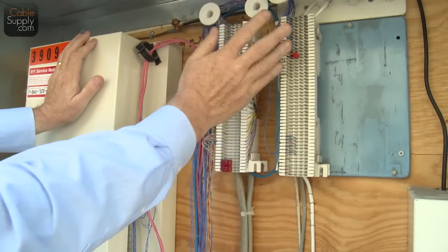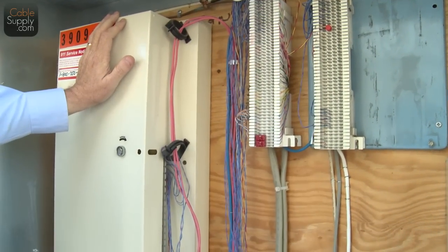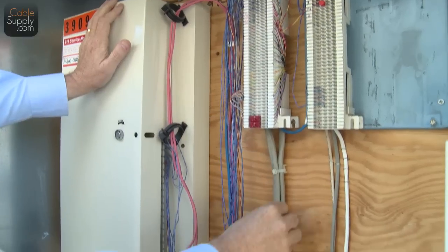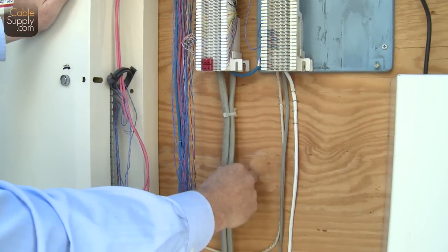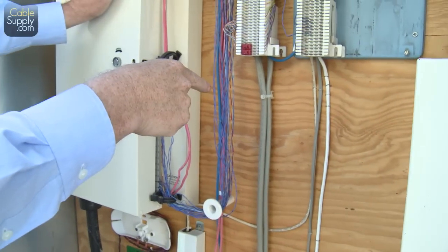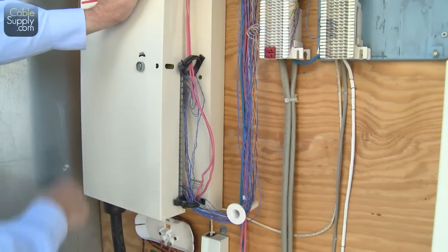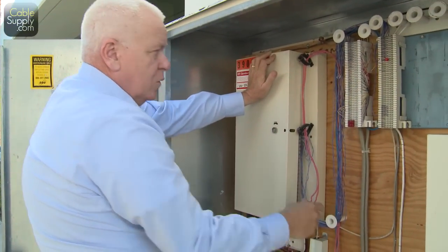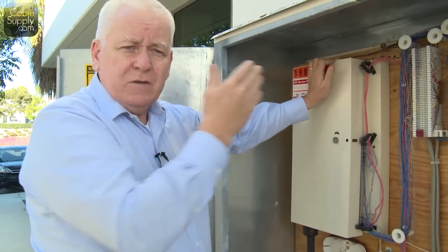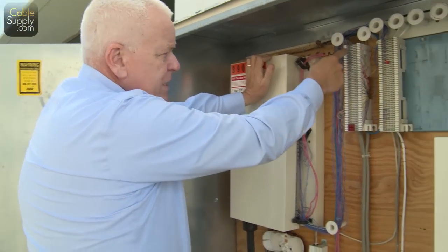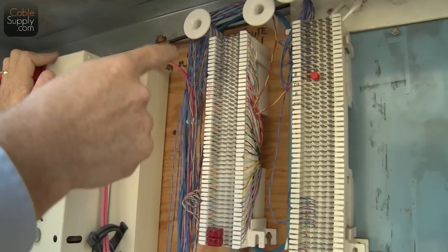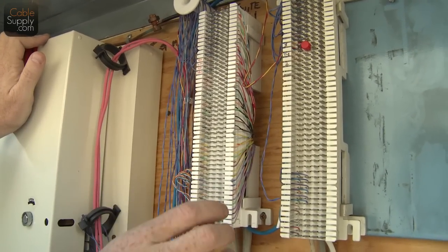This should have a little door on it. A little red door is normally what you find on this, and it just doesn't have one. Then it goes from here, it goes over these 25 pair of cables into the building. So the circuits come up here, into here, over to here, into the building. Where the responsibility of this circuit ends is right on this side of this block. It's a split 66 block, and it's a 21X.